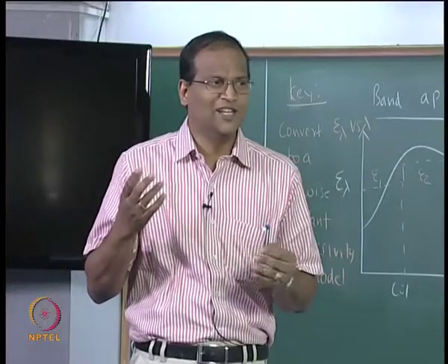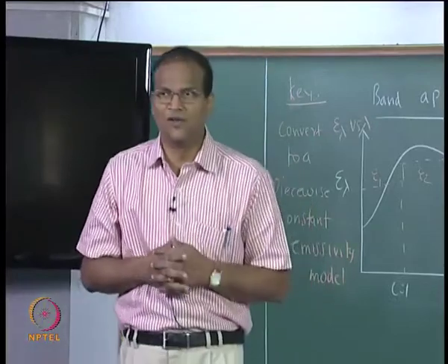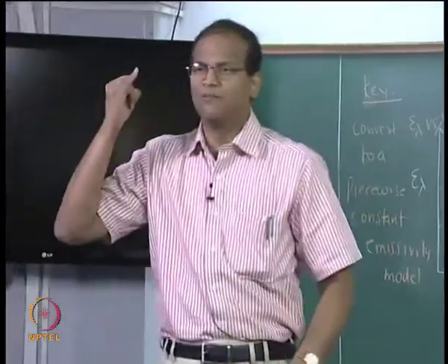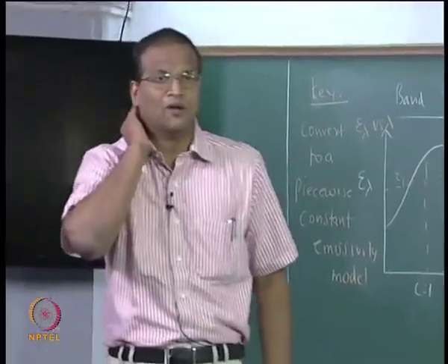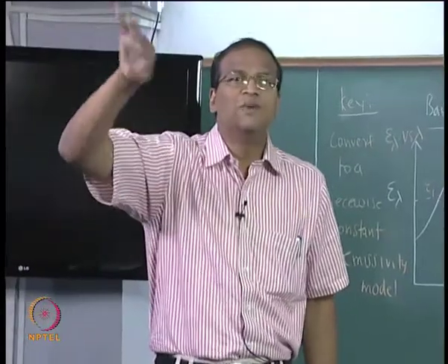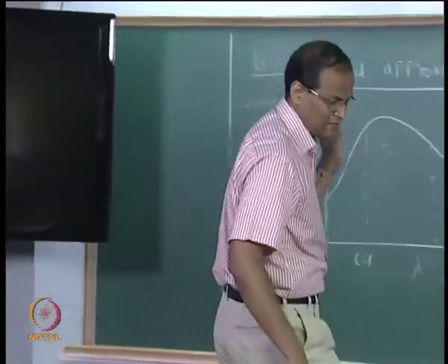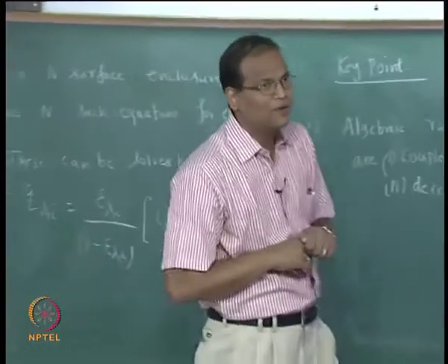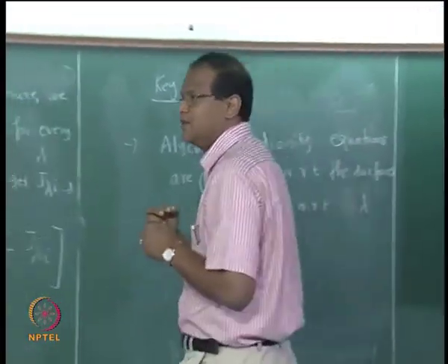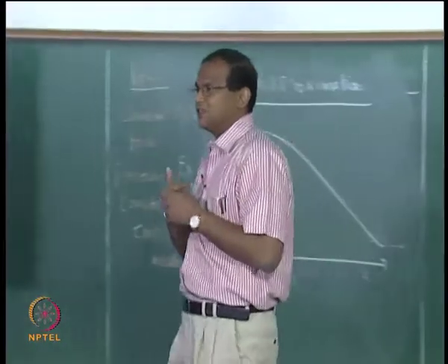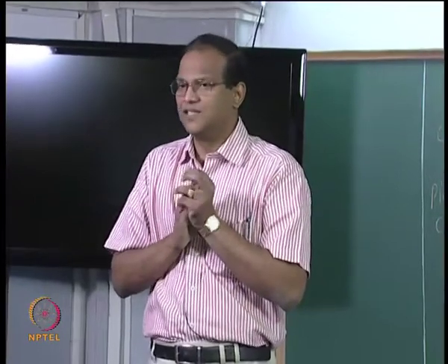Accuracy will also increase as we employ more bands, but it is a trade off between your computational cost and accuracy, right? So accuracy will increase with number of bands, complexity will also increase with number of bands. Accuracy is also critically dependent on how good this piecewise model approximates the non-grey body behavior. That is the final point which I have said is very important. So finally the accuracy of the calculation depends on how good this piecewise constant emissivity model mimics the actual non-gray behavior of the surfaces under question.